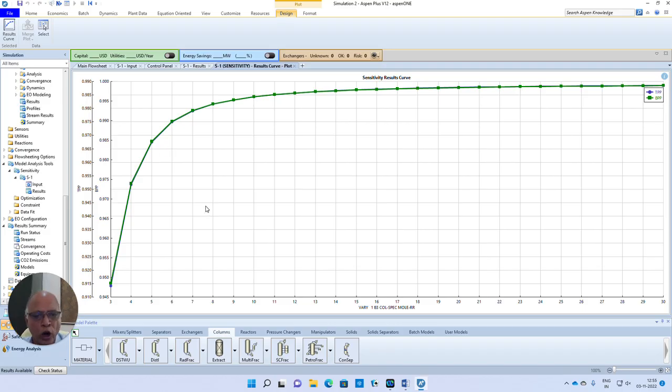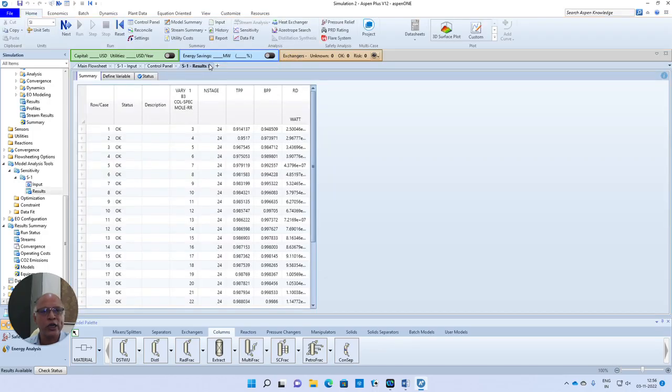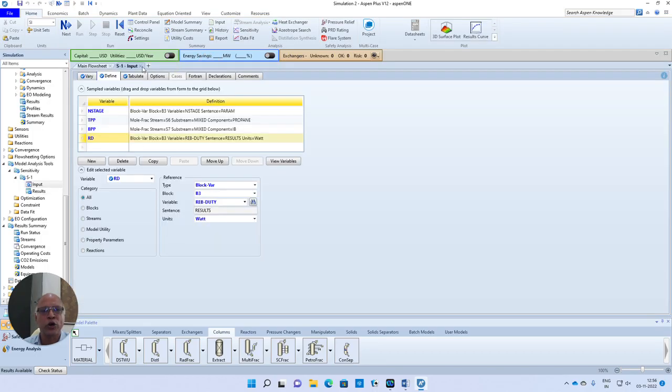So depending on whatever purity that you want, for example, if you want to keep the number of stages constant, and if you would like to obtain a purity of 0.98, now you can practically observe what should be the reflux ratio that you have to use. Right? So around 4.5 or something like that. You can always use a design spec to fine tune whatever is your requirement. But try to observe the difference between what has been specified and what is being calculated in both these models.